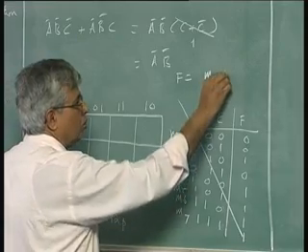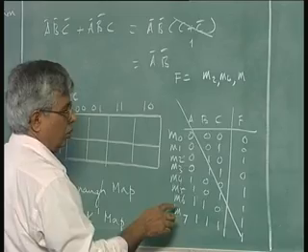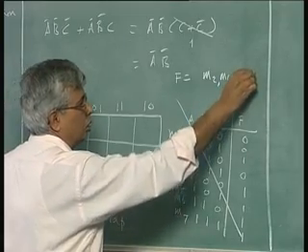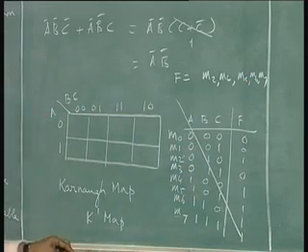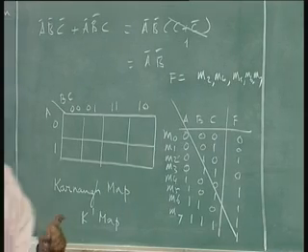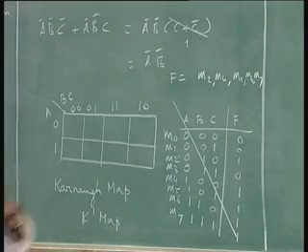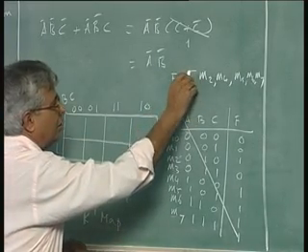minterm m4, m5, minterm m6, minterm m7. For these minterms, output is true or 1. Since it is a sum of product expression, remember each of these is a product term, I represent it by a sigma.